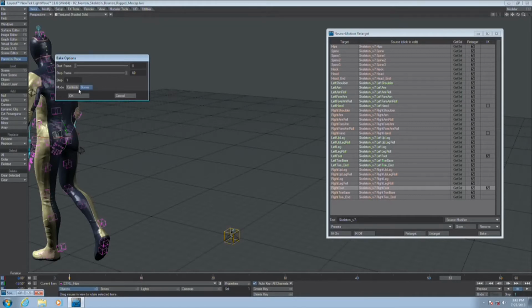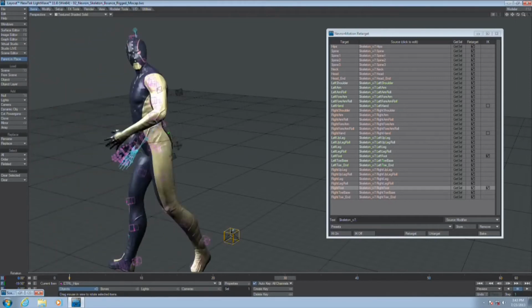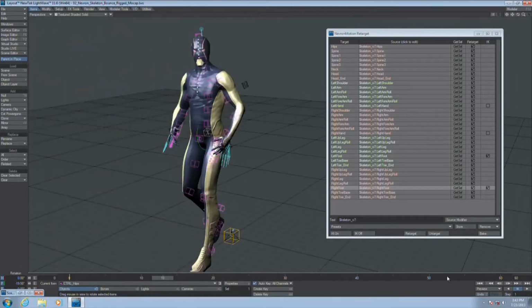And of course, once we have baked the animation, we can get rid of the motion capture skeleton we have imported. Okay, all the stuff we don't need anymore. We just get what we need. And we can create an actor to be used in Motion Mixer, which is very useful because you can stretch. Right, because you have clips in Motion Mixer that can be scaled over time and reused, mixed with other motions. That's very useful. So this is what we call retargeting, but we support the Kinect.